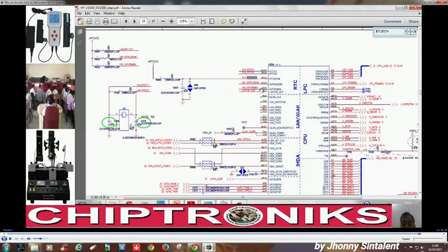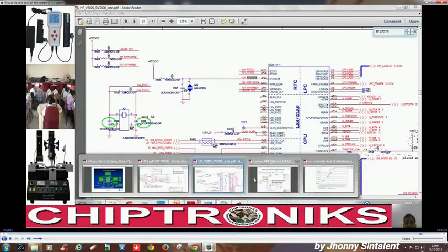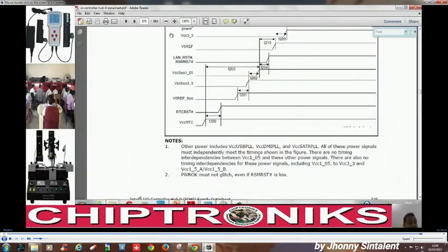And the third thing is ICH INT VRMEN. What is VRMEN? Internal voltage regulator enable, and this internal voltage regulator enable is connected to 3 volt. So this signal is active, as we had already discussed in our features page.